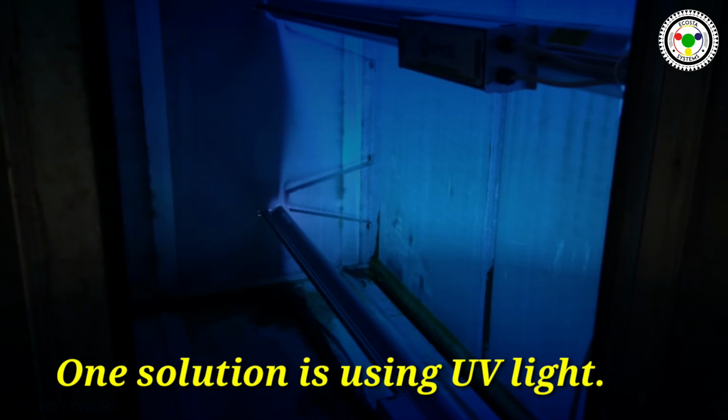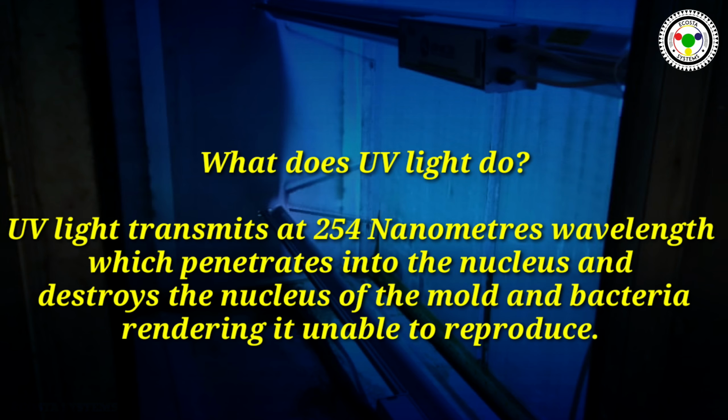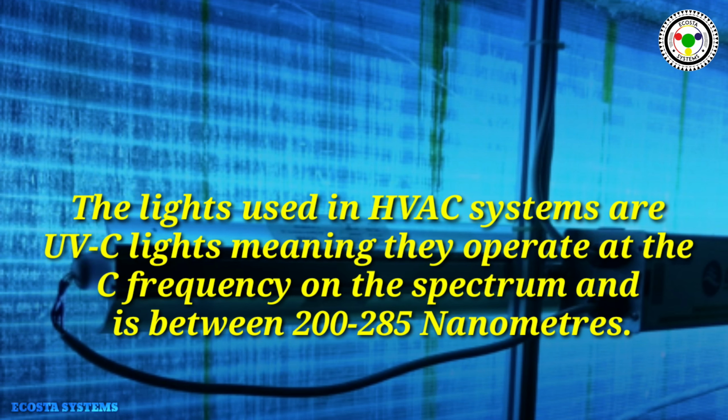One solution is using UV light. What does UV light do? UV light transmits at 254 nanometers wavelength, which penetrates into the nucleus and destroys the nucleus of the mold and bacteria, rendering it unable to reproduce. The lights used in HVAC systems are UVC lights, meaning they operate at the C frequency on the spectrum and are between 200 to 285 nanometers.